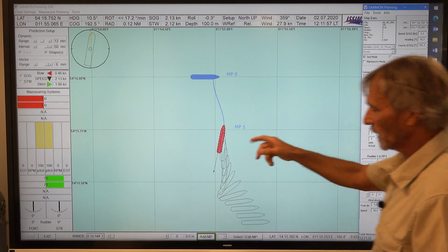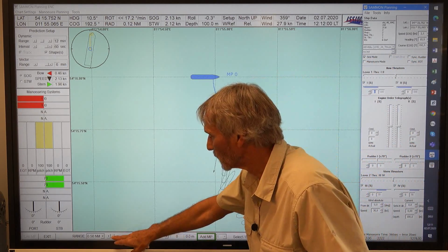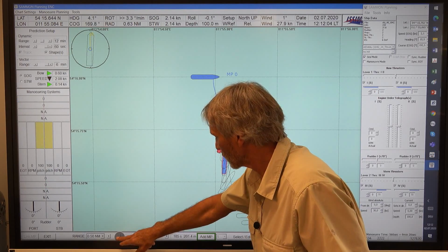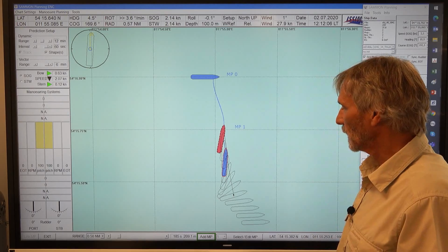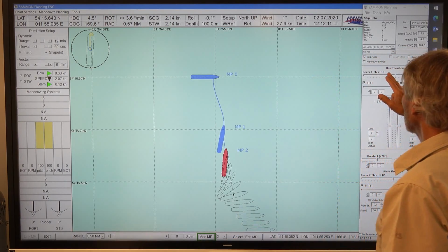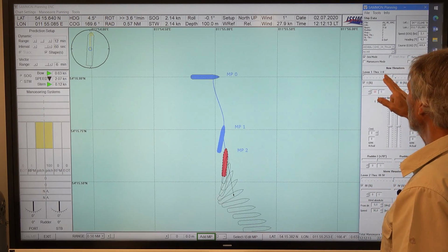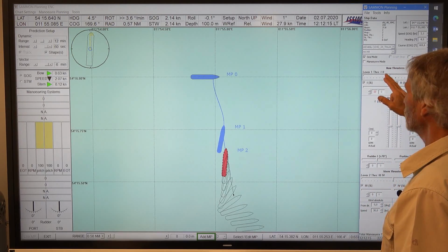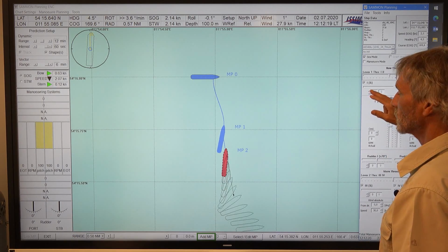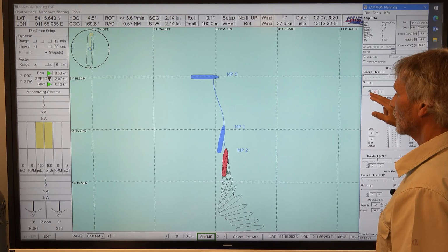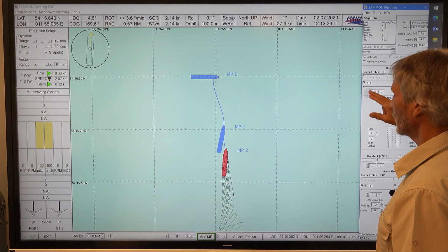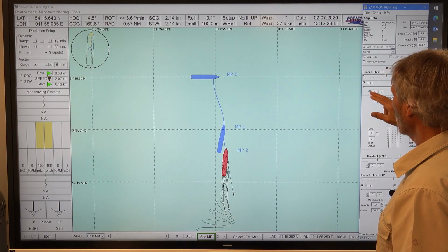Okay, so we can use the time slider to move the ship a little bit downwind, like here. And there's a new maneuvering point where we will set the bow thruster to the other side to stabilize the vessel. We can do that several times to find the balance, the situation where the ship is drifting with the bow in the wind.